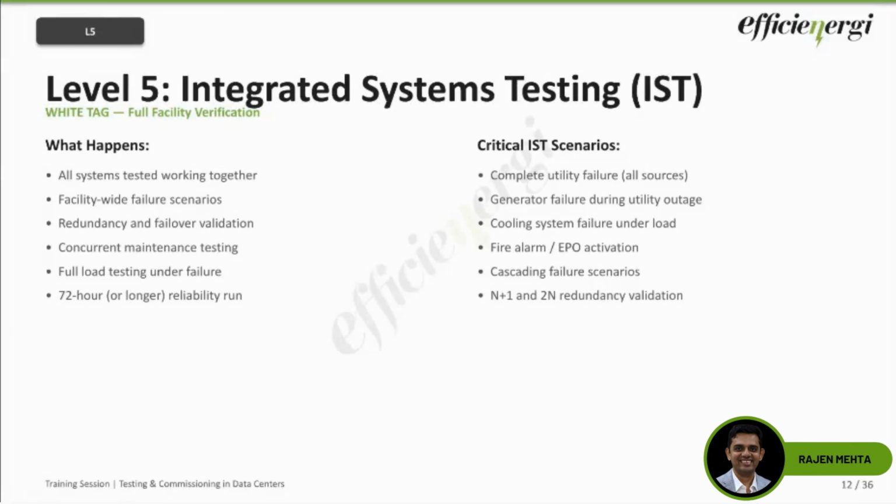Then cooling failure scenarios you will also test, where you ensure that the IT load keeps running while you disable, say, one cooling unit. All the remaining units should be able to maintain the temperature, and no thermal shutdown can occur during this failure scenario. And there is also an important aspect, that is pre-IST.